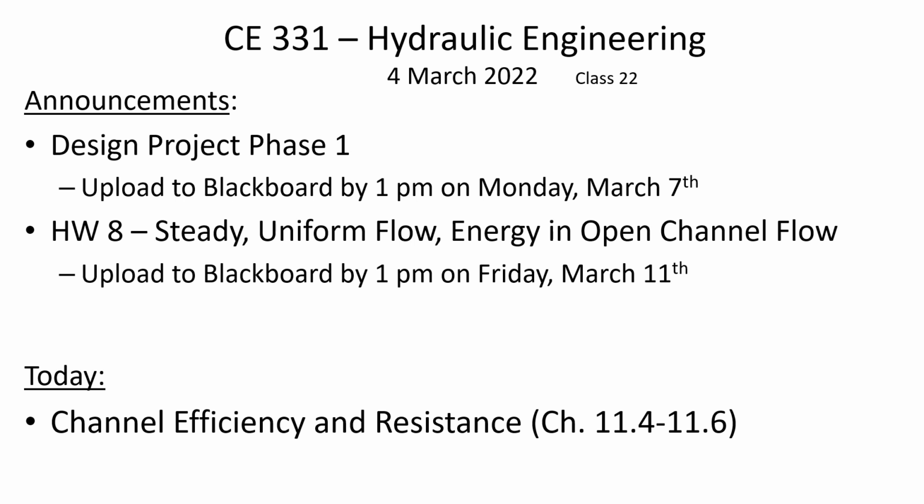So that's due on Monday, and then I'll take next week and spring break week to be looking over it and giving you feedback that you can adjust before you finalize your pipe sizing. Because of course, the pipe sizing that you do in phase 2 depends on the flow rates. And so you need to have a good idea of what flow rates ought to go into WaterCAD when you're sizing the pipes.